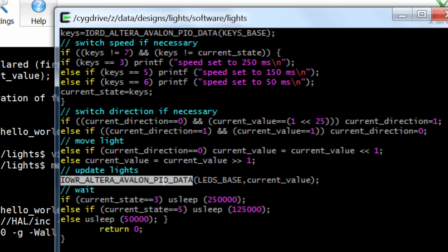Where that's 6 and that's 0, right? But remember that these things are active low, meaning that a 0 bit turns on the segment and a 1 bit turns it off. So you actually have to invert this whole thing like that, right? And what is that? That's 0, 1, 2, 3, 4.